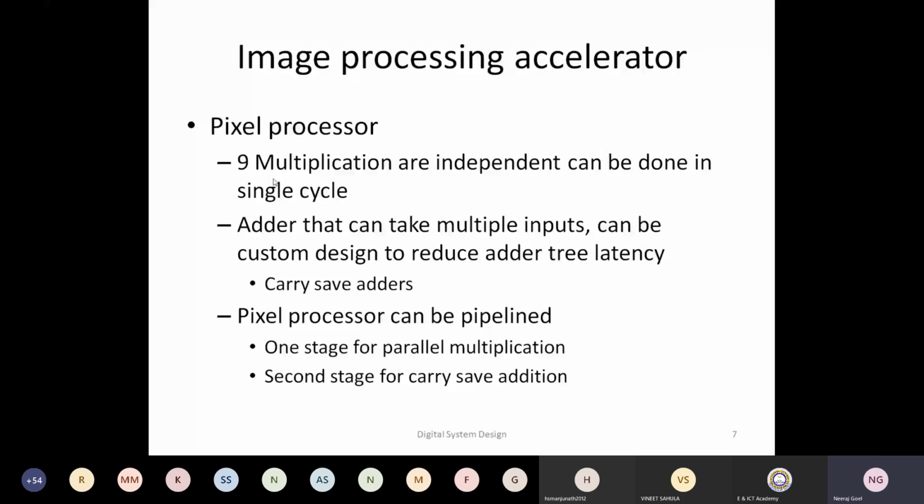For example, a 32-bit multiplication would add 32 partial results. And to add those partial results, a specific type of adders called carry save adders have been designed. These carry save adders are very specific adders which can take multiple inputs. So even here we require 9 inputs to be added. Those 9 inputs can be added together by just looking at what can be added in parallel. These specific units can be created for specific applications.